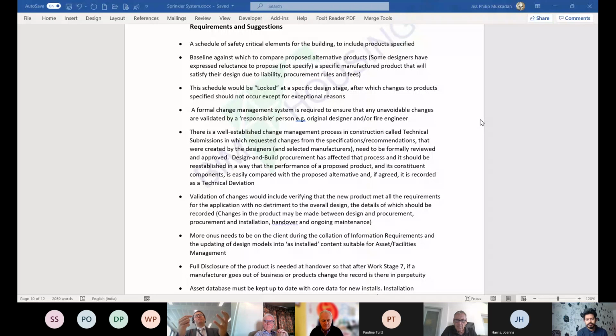Because the problem is the sizing of the tanks, hydraulic calculations, and whether it's Cat A with an office ceiling or non-office ceiling. If you've got no ceiling, your heads are above where the ceiling void would have been. The obstacle rules have all been clarified now, so you need these guys on pretty early.